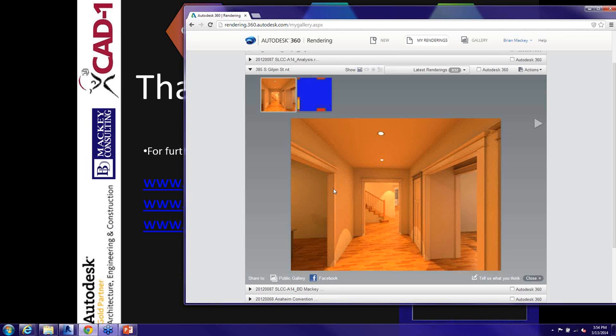So a lot of times for me, rather than doing a draft in Revit, I'll do a draft off of the cloud to see what's going on. Do my light sources light up? Because if I didn't have an IES, those would be black. Did I get materials assigned to all of my objects? Oh man, I missed the material on this door and this door.